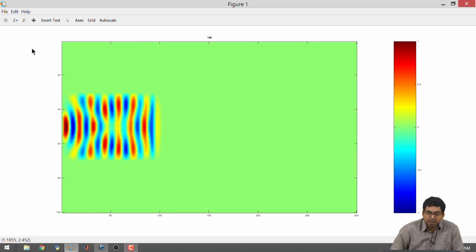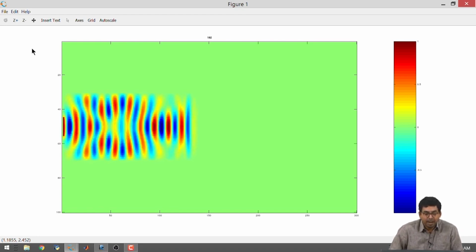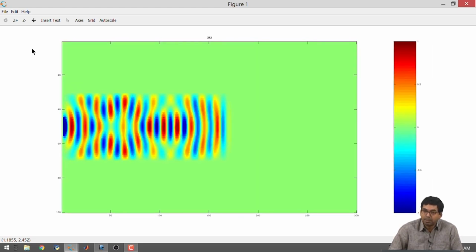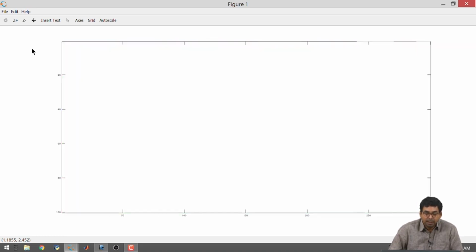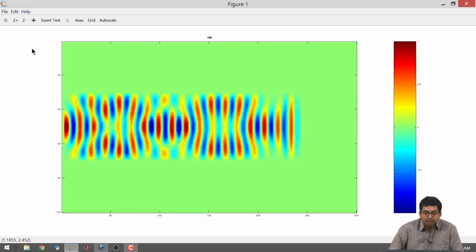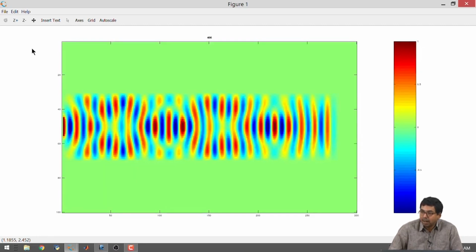Okay, now it is possible to say that maybe this waveguide is supporting multiple modes, and I can see that in some regions it is forming 2 spots, some regions it is forming 1 spot, etc. Right. So, clearly the electric field distribution across the cross section is different in different places, right, and there is some periodicity happening, right. So, size of your source could also determine how many modes you are exciting probably, right.